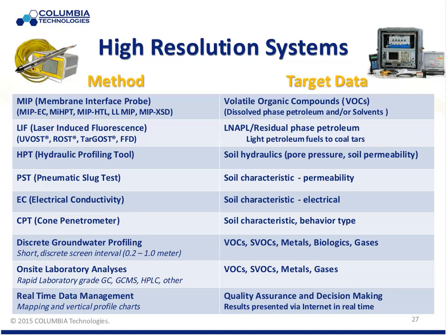Hydraulic profiling tool, HPT, has been out there now for a little over a year and a half, 2 years. Excellent tool for really evaluating what's going on in these pore spaces, which soils are going to be permeable or allow for fluid flow, which ones are not. Similar tool, pneumatic slug testing, can be put on your existing wells and in the formation next to it, so you can do a comparison. Is my well really reacting or performing to my subsurface? Is the subsurface in the well giving me the same information?